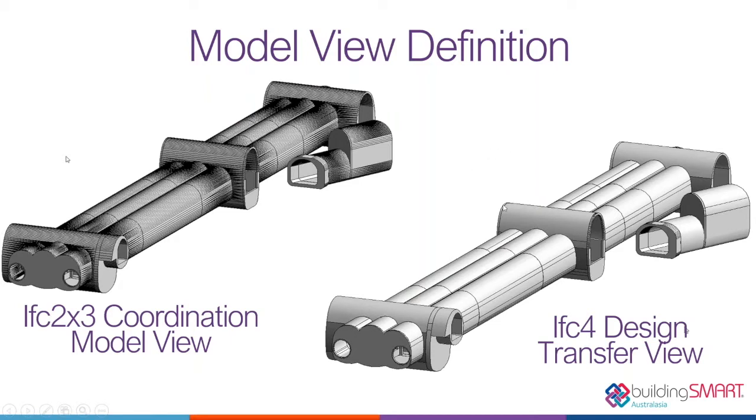And there's only now, 6 years into IFC 4, some certifications which are emerging for a reference view. A reference view is more a visualization view of IFC. So you'd expect to see primitive shape representations like the one on the left, which are mesh faceted descriptions for the geometry. IFC 4 includes a lot of improvements, particularly NURBS and other history-based shape representations for sweeps, etc. So you will get higher quality models with IFC 4. It's just the reliability might be less.